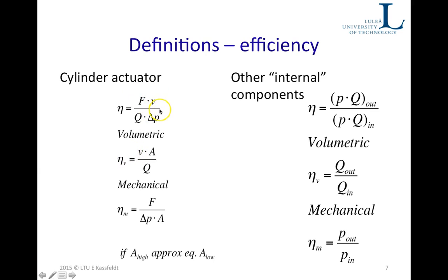This actuator. You can divide it into a volumetric efficiency and a mechanical efficiency, and the volumetric is connected to everything that moves, the velocity times the area divided by the flow. The mechanical is related to the forces, the force divided by the pressure difference times the area.